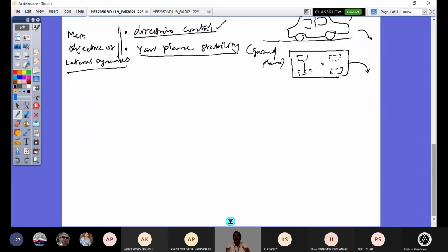I will have different brands of vehicle. I'll have different types of vehicle, in the sense of hatchback, sedan class or SUVs. These are the three groups of vehicle that we call of any particular brand. All these vehicles that I have in my hand, I have to talk about their capability of handling. I don't even require these three equations, which are already further simplified. One simple equation is sufficient, to look at all these vehicles, how they are executing their steady state motion. So that's one equation itself as lateral dynamics.